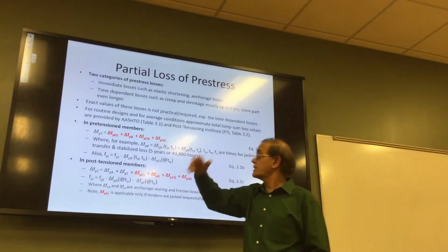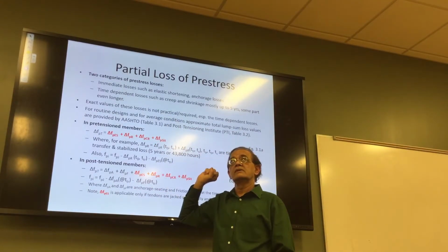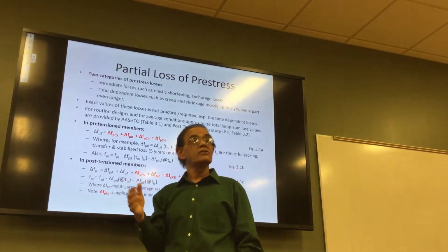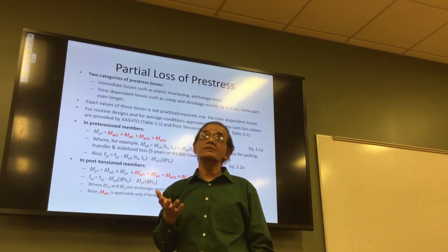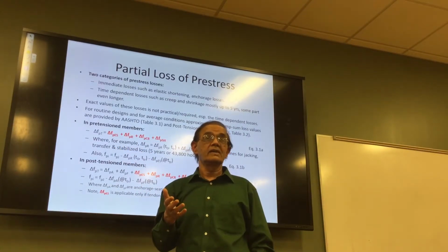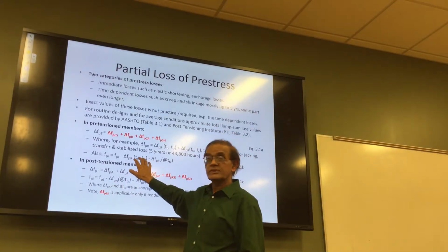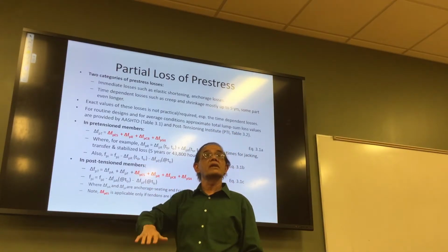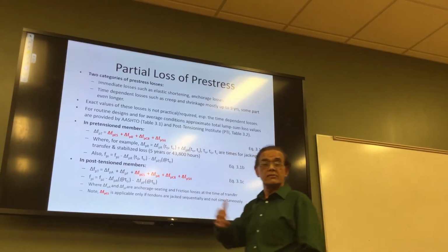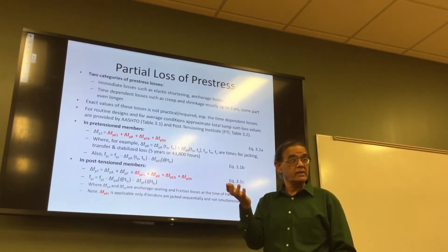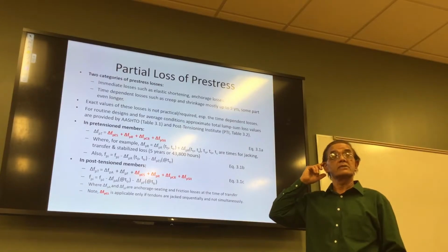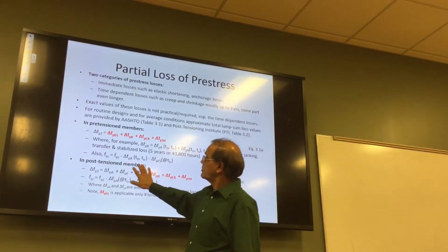So we need to keep that in mind in case of post-tensioning, because the good thing about that is, if you have waited for say 2 months, now you have a stronger material, right? 2 months means it's way beyond your 28 day compressive strength, right? Versus this one where you're applying your stresses already at a very low level, like 50% of 28 day strength, or even less, depending on how you cured it. If you cure with steam, then it is quicker. If you cure with moisture, with water and spray and all that, then it is not as quick. So you have to keep that in mind in post-tension.